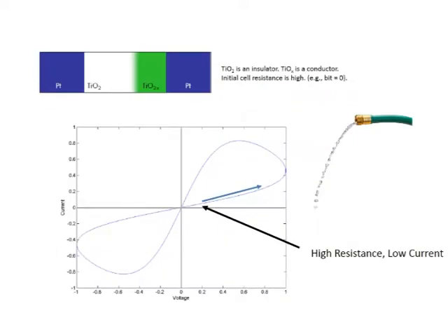The first memristor was made out of titanium dioxide, or TiO2. TiO2 is an insulator. However, if you make the device using titanium with oxygen vacancies, the resulting TiOX is a conductor. More TiO2 drives higher device resistance, and more TiOX drives lower device resistance.